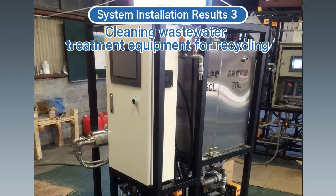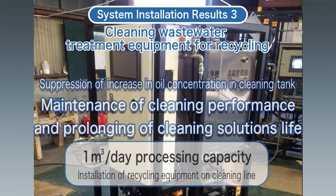This is a result of the treatment of the wastewater from cleaning. The constant filtering of the cleaning solutions in the tank with the UF membrane means that the increase in the oil concentration is suppressed, and the cleaning performance is maintained over a long period. The level of contamination of the cleaning fluid is suppressed, so the length of the use of the cleaning solutions before replacement is greatly extended. This reduces the frequency of the work to replace the fluid and the cost of disposing of it.